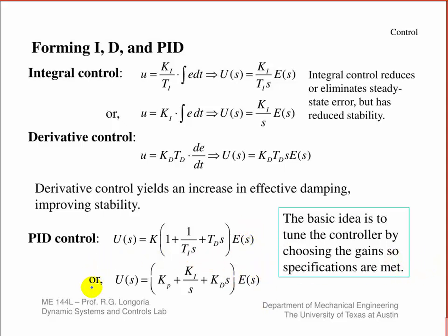Okay, so once you have this control, so let's think about the PID here. Once you have this controller set up, your job is to find what gains will give me the overall system behavior that I like, and that's what tuning is all about.